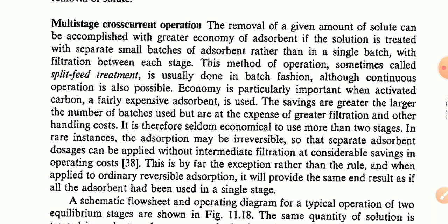The economy is particularly important when activated carbon, a fairly expensive adsorbent, is used. The savings are greater the larger the number of batches used, but at the expense of greater filtration and other handling cost. It is therefore seldom economical to use more than 2 stages.